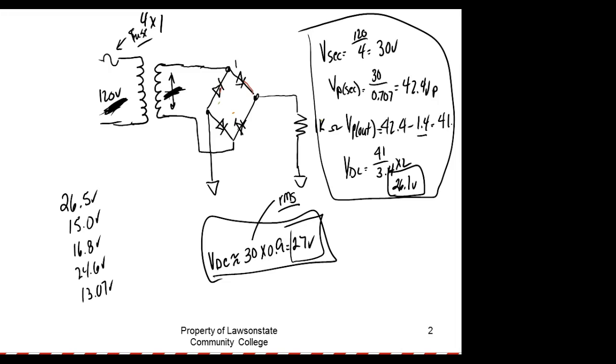So that means you can measure this voltage at your house, and it'll be one thing. If they're on a different transformer, you could go to your mother's house and measure it, and they'll have a different voltage. Because NEC can't say exactly what voltage you have. Because when Alabama Power generates voltage, it's regulated when they generate it, but they have to send it over all them wires, right? You understand that? And then they compensate it with tap transformers. So they try to compensate with tap transformers, but they can't have an infinite number of taps to give you exactly 240 and 120. But so that's what the National Electrical Code is.